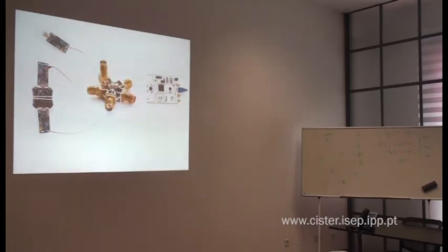So in order to do that, you have to build this piece. This is basically a multi-port device. It takes the carrier frequency, a very high frequency, 2.4 gigahertz, and gives you a constant attenuation through all the ports. So you put a signal here, and the amplitude that you get here is all the same. And you can also guarantee that there is impedance matching, so there are no reflections of the signal. It's rather simple.